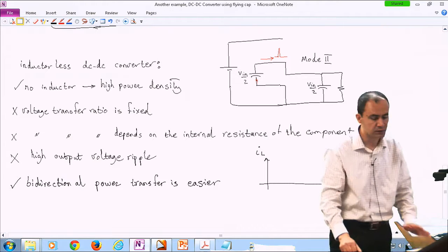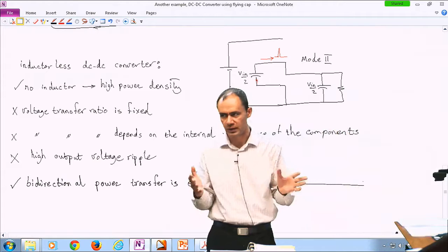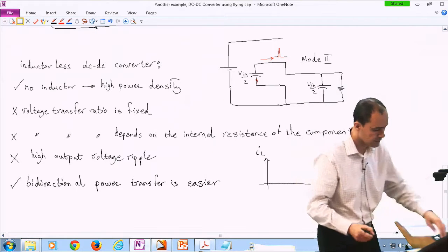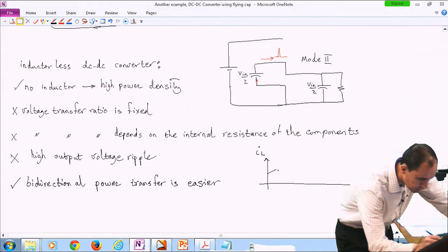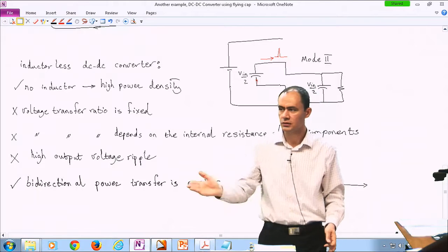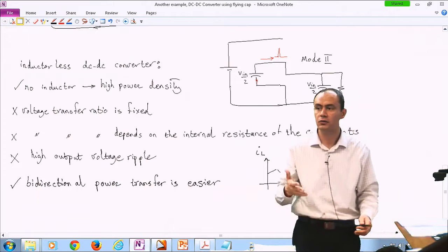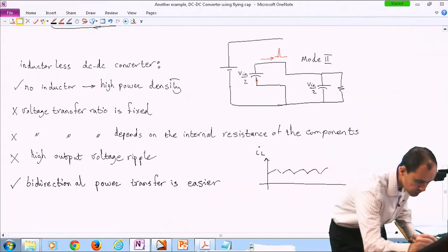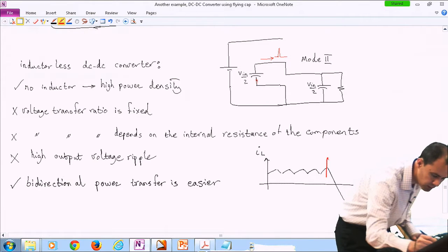And this buck converter is, for instance, transferring power from a high voltage battery to a low voltage battery, for instance, in a hybrid vehicle. If you decide to change the direction of your power flow, let's say previously you were operating like this, for instance, the vehicle was accelerating, then all of a sudden the driver puts on brakes and you want to send energy back or something like this. So you want to go to a negative value for your inductor current. But remember, inductors have limitations, a slope limitation, so it's going to be like this. So it's going to take some while